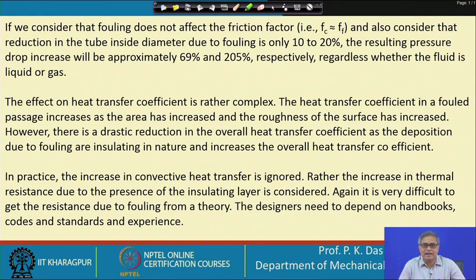So, we cannot neglect the deterioration in overall heat transfer due to the appearance of a new resistance. Convective heat transfer coefficient probably is increasing, but there is appearance of a new resistance due to the deposition of the foulant, and that we cannot neglect. So, that is why the effect of fouling in almost all the cases is that it will deteriorate the performance as a heat exchange device.